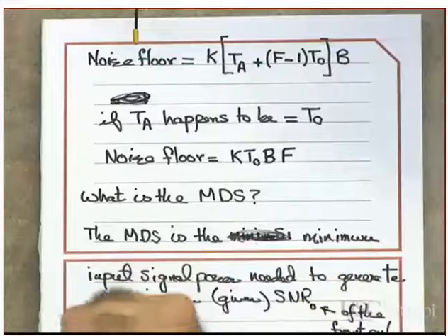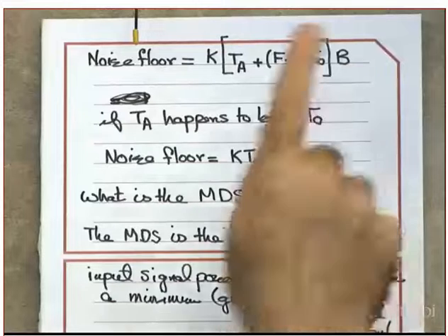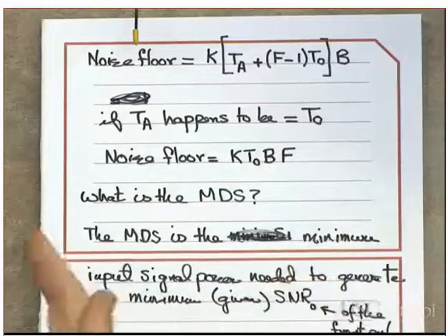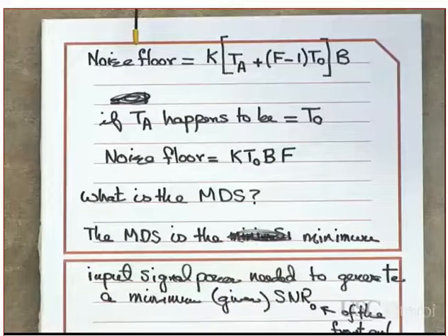Yes or no? In other words, do not put the band select bandwidth. Remember, the first filter was the band select. You need to put the bandwidth of the channel select. Yes or no? Why? Which one is wider, the channel select or the band select? The band select. But it does not make sense that you take the band select, even though the noise power increased, because it will not affect the demodulator, since you are going to go through the channel select first. Yes or no?